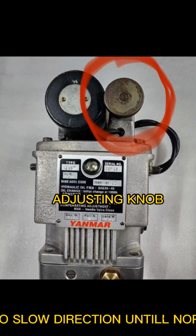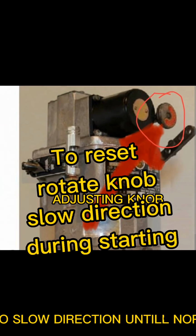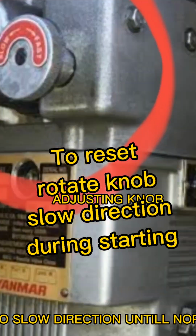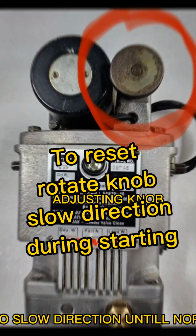If you ever use this kind of testing, you need to reset. While running the engine, you need to adjust the knob in the slow direction until normal RPM is reached to avoid an overspeed trip again during starting. Check also the frequency meter in the panel.